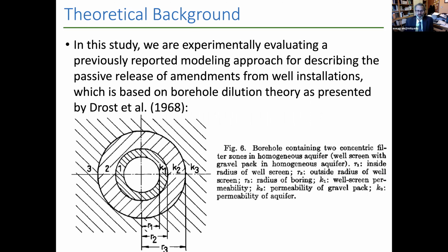And the tool we're using is what others have used to describe this, but I think we looked at it a little more closely, is borehole dilution theory. So this is what happens when the flow of groundwater reaches an unpumped well. The well has a higher hydraulic conductivity or permeability than the material around it. So this affects the flow. The water wants to flow into that well and out of it.